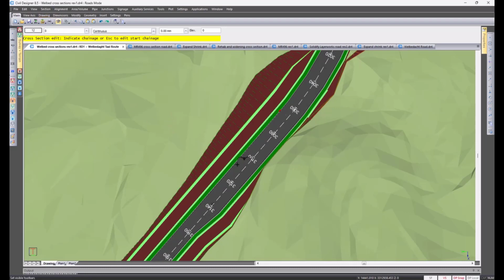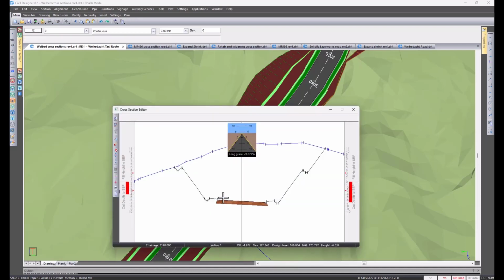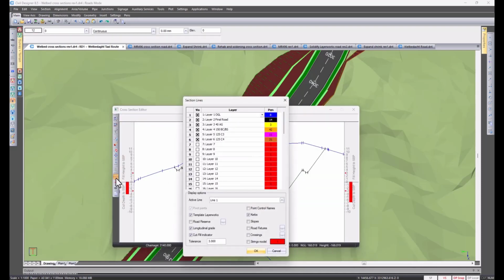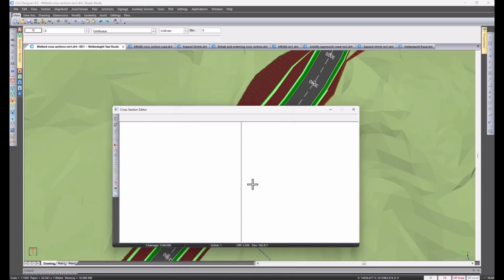The section graphical edit. We'll just have a look at those points on layer 10. So I'm going to switch that on. Let me just, I have to switch off some of these. I can switch off the final design layer, switch off the layer works. Okay, so basically those are the points. So we've got our road edges and we've got our center line.